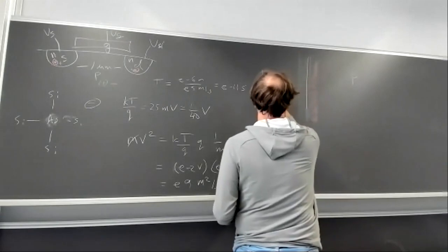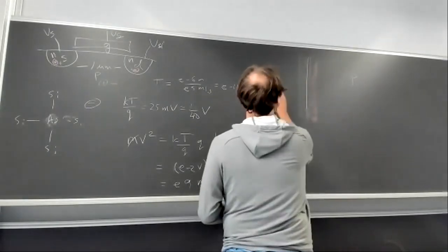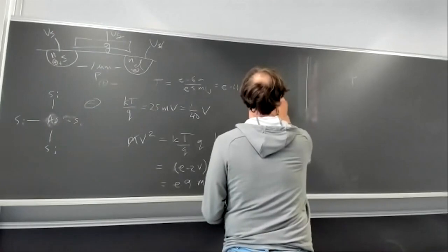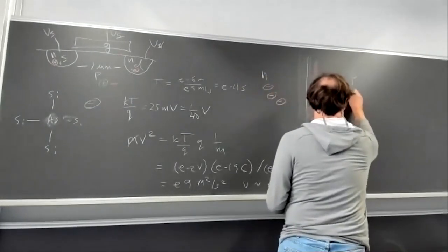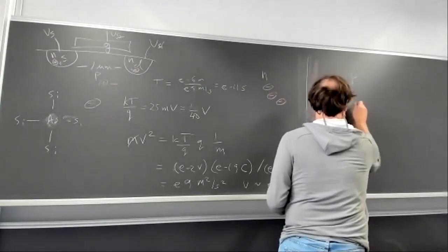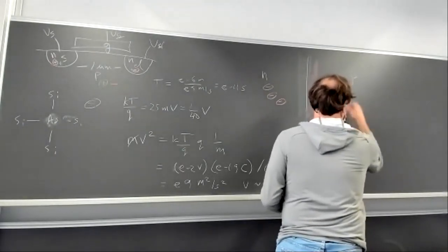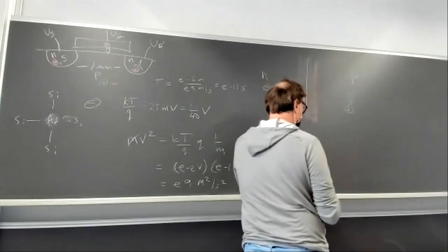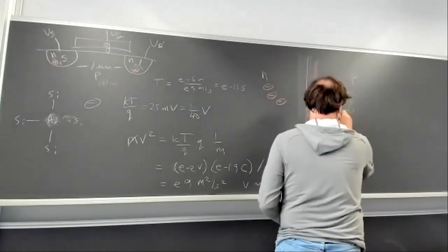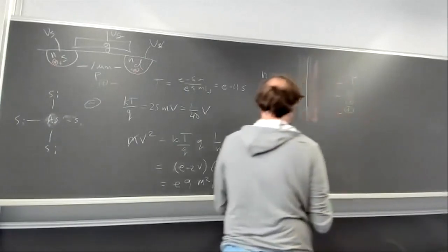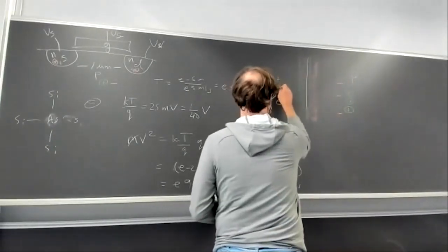And over here, you're going to have lots and lots of free electrons still. Over here, lots of free holes. It may be a different doping on each side. Here you'll have some fixed ions so that it's equal. It has to be neutral. And here's some fixed positive.